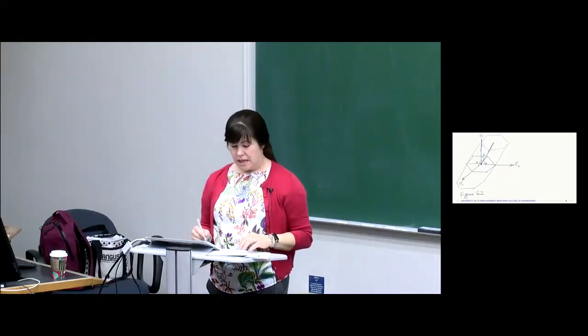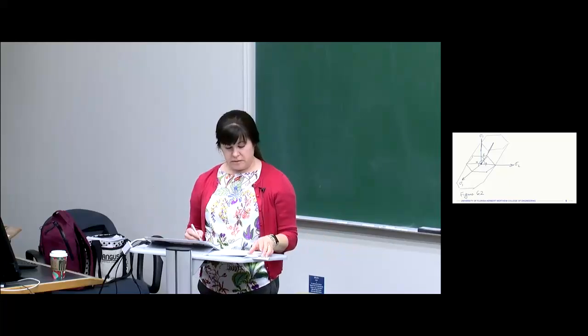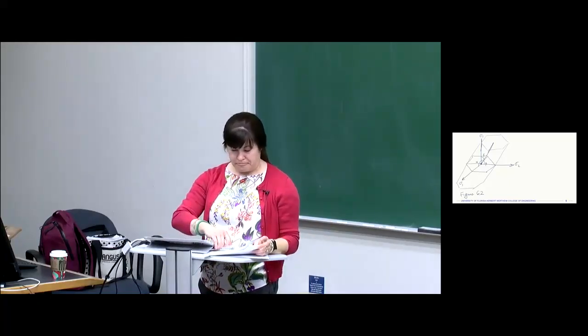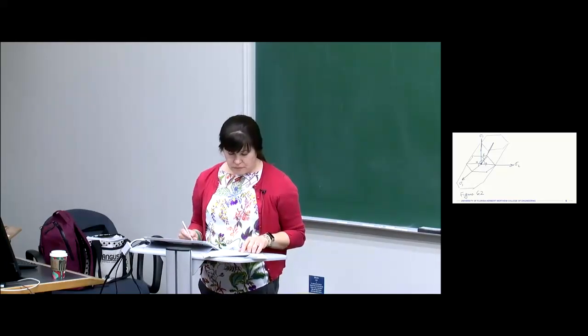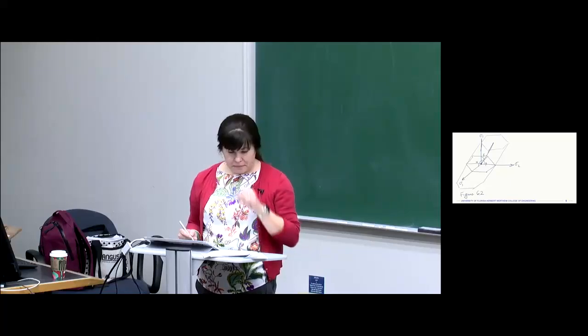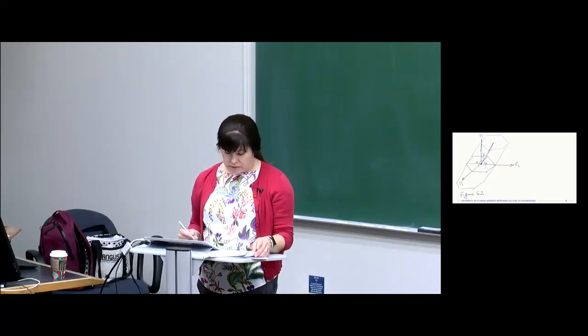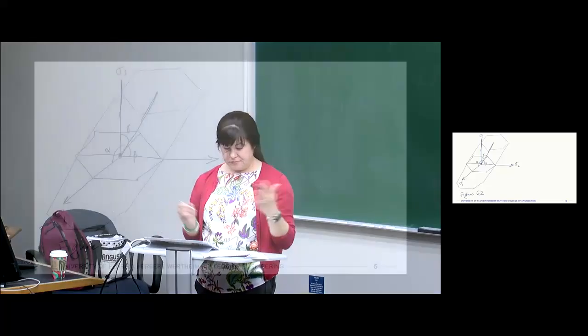So you should definitely look in the textbook for a much better drawing of this. And so that's our safety envelope in 3D. And anything outside of that, we would predict yielding. Okay. So that's the Tresca or maximum shear stress theory.